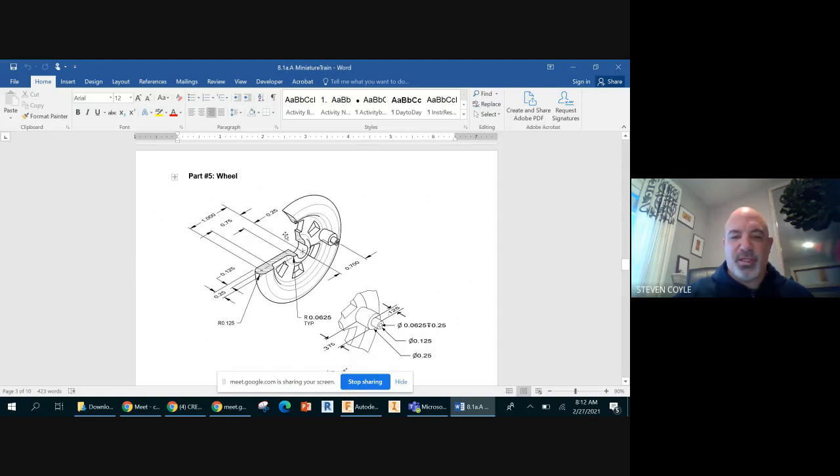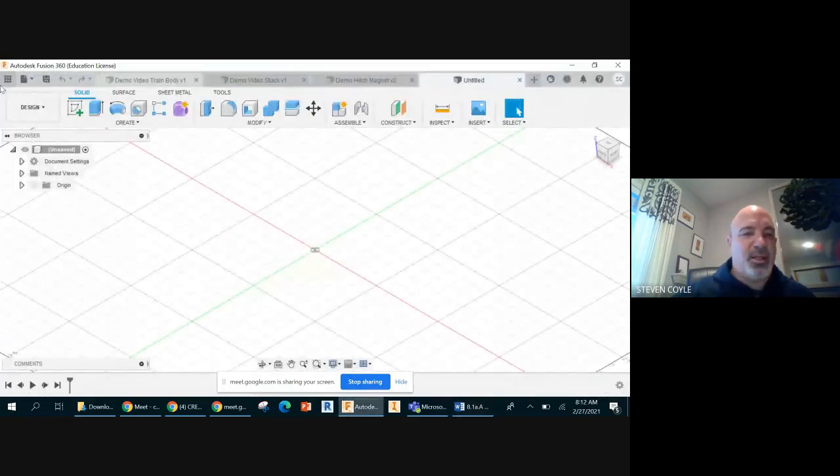If we take a look at it, it's 0.25 away from here, so half of that roughly looks about half. They should have better dimensioning on here. So I'm going to say that this is 0.125 away from here. This one is going to be 0.125. And if I follow this all the way across, it's going to tell me that the height of it is 0.25. So right now I'm just going to draw this rectangle spaced away from that line.